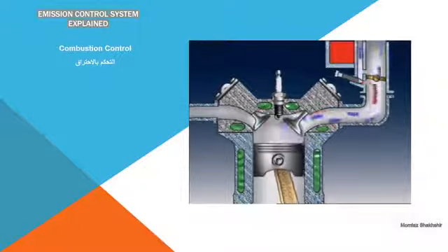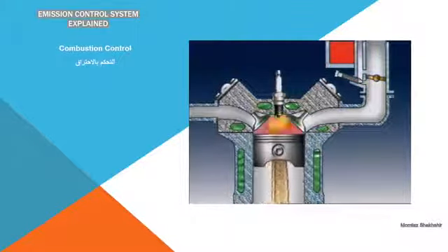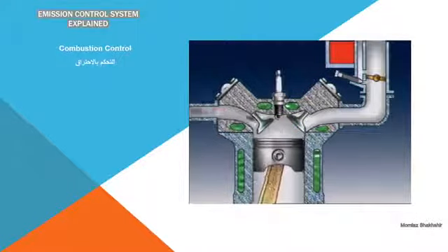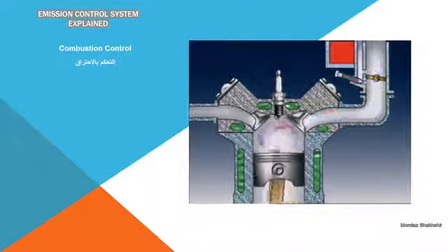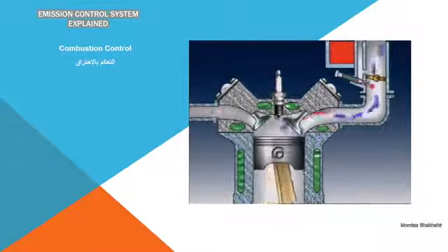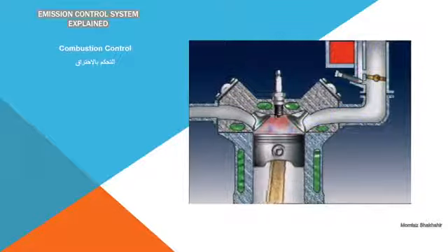There is only a relatively small quantity of mixture in the combustion chamber at this point, so turbulence tends to be poor. This can lead to incomplete combustion and the release of unburned gases into the exhaust.